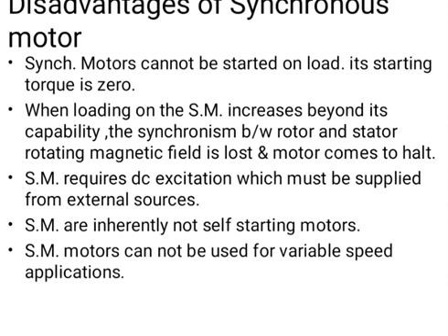Now there are some disadvantages of the synchronous motor. First, a synchronous motor cannot be started on load, that means its starting torque is 0. Second, when loading on the synchronous motor increases beyond its capability, the synchronism between the rotor and stator rotating magnetic field is lost and the motor comes to a halt.